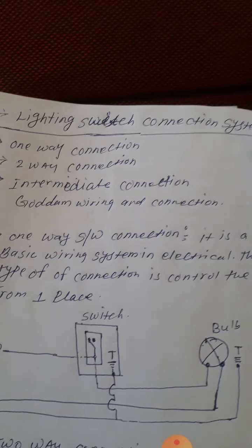If you enter wiring, first you should take the knowledge of one way basic wiring. We can do wiring in lighting and anywhere. In single phase there are 3 wires: one phase, one neutral and one earth. In our country we often do not give the earth, but this is wrong. If you make standard wiring, you should give the earth. Earth is needed to protect your equipment and protect you from electrical shock.